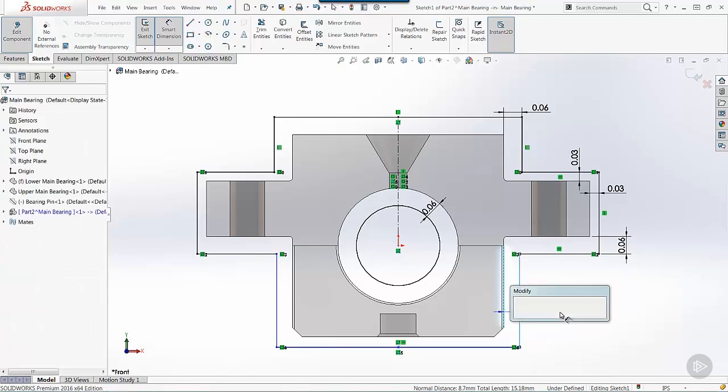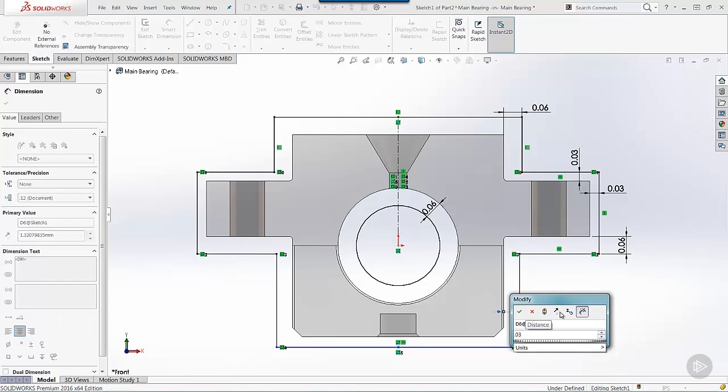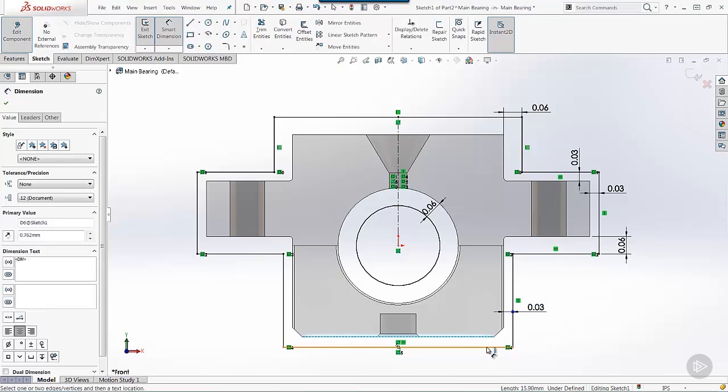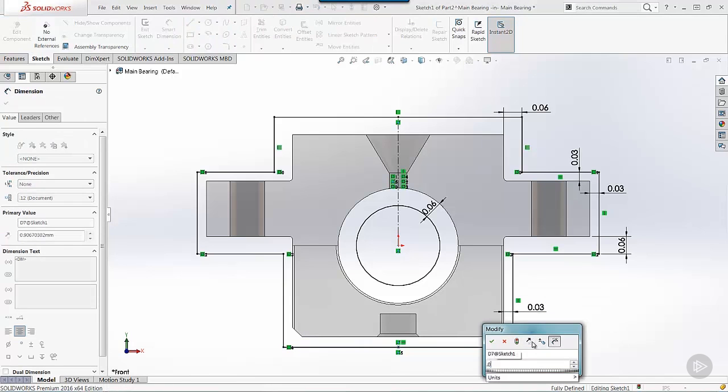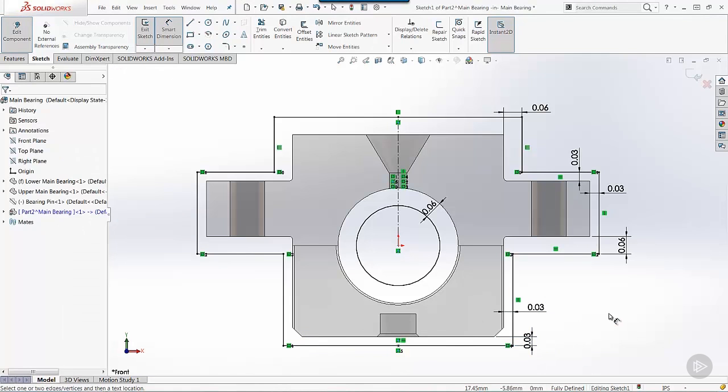Down here, this is another situation where I need a minimal amount of material, and then on the bottom as well. It's up to your design intent, your liking. Some would argue that I need more material here on the bottom. Again, it's up to your discretion, design intent. And if you'll notice, I'm also not adding any fillets. I think all fillets and draft need to be added as a secondary operation. We've got our sketch where we want it. Now we're ready to make the extrude.